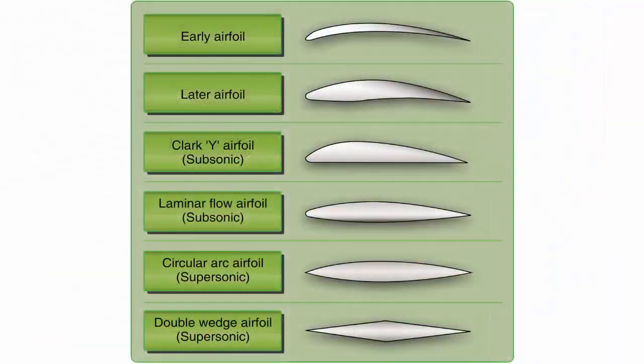The most efficient airfoil for producing the greatest lift is one that has a concave or scooped-out lower surface. As a fixed design, this type of airfoil sacrifices too much speed while producing lift and is not suitable for high-speed flight. On the other hand, an airfoil that is perfectly streamlined and offers little wind resistance sometimes does not have enough lifting power to take the airplane off the ground. Thus, modern airplanes have airfoils that strike a middle ground between extremes in design. The shape varies according to the needs of the airplane for which it's designed.